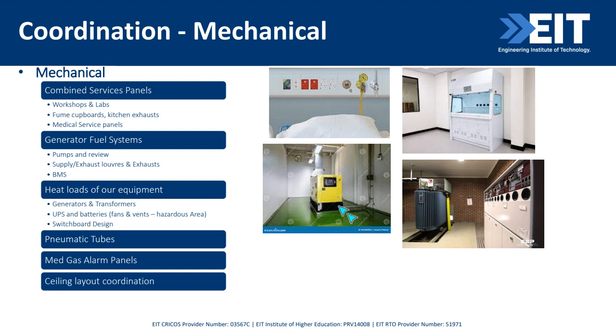If we're installing a generator, we need to let mechanical know because they'll need to look at what ventilation is needed, how to extract the heat that gets pushed out into that generator room. Similarly with fuel system supplies. Do we have ventilation for any fumes and appropriate exhausts?